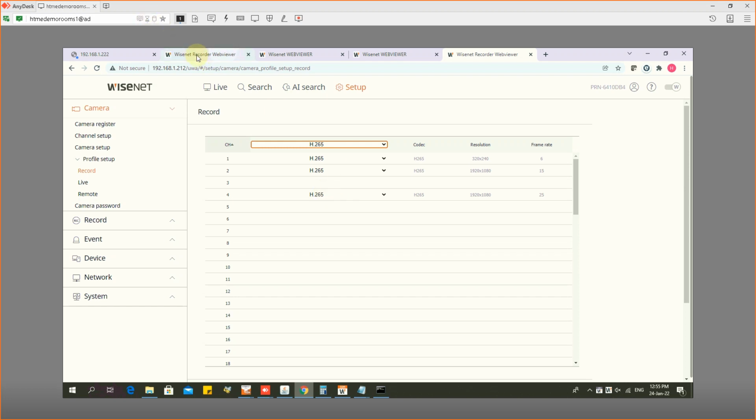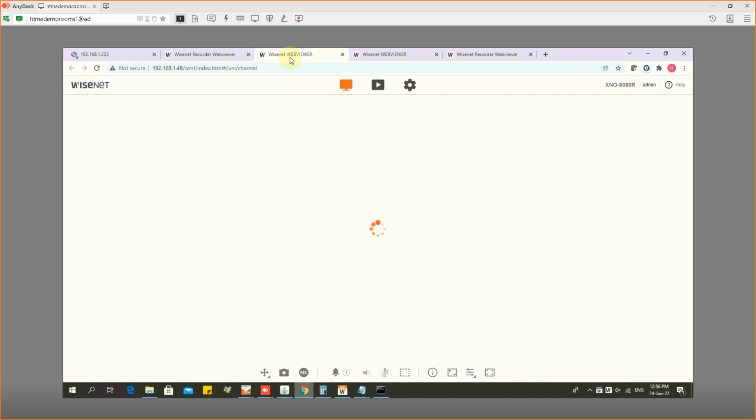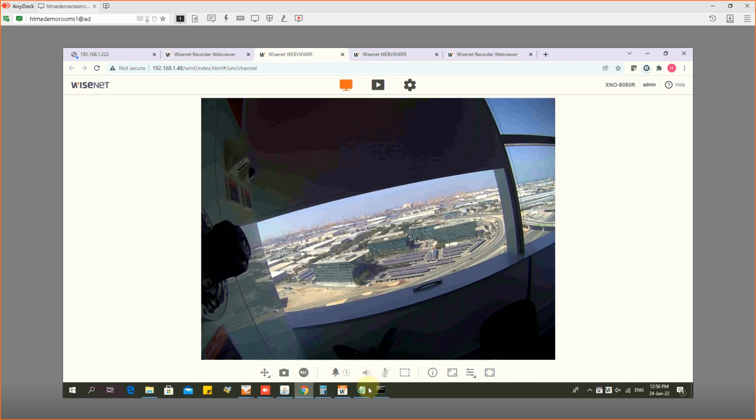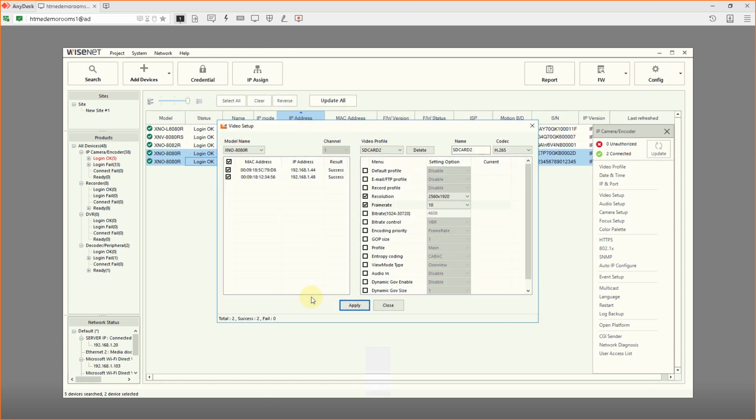Done. You are only preparing the camera using device manager. You are checking, making all the settings according to the project requirement. Instead of doing camera by camera, you're doing it through the device manager. You are preparing H.265, 10 frames, preparing everything and keeping it ready. Once you connect to maybe Milestone, in Milestone, you change profile for recording to H.265. You connect to our NVR, you change in the NVR profile H.265.